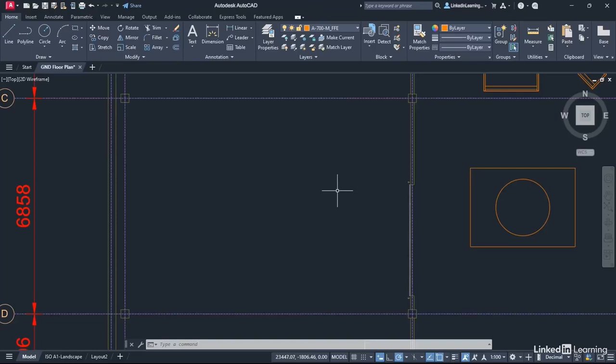polar. Come down to the status bar. There's polar tracking there. Ortho is this one. It's a little right angle symbol. Click on it and you'll notice that polar automatically turns off. You cannot run polar at the same time as ortho and vice versa. So we've got ortho switched on now. Let's go back to that polyline command here on the draw panel.